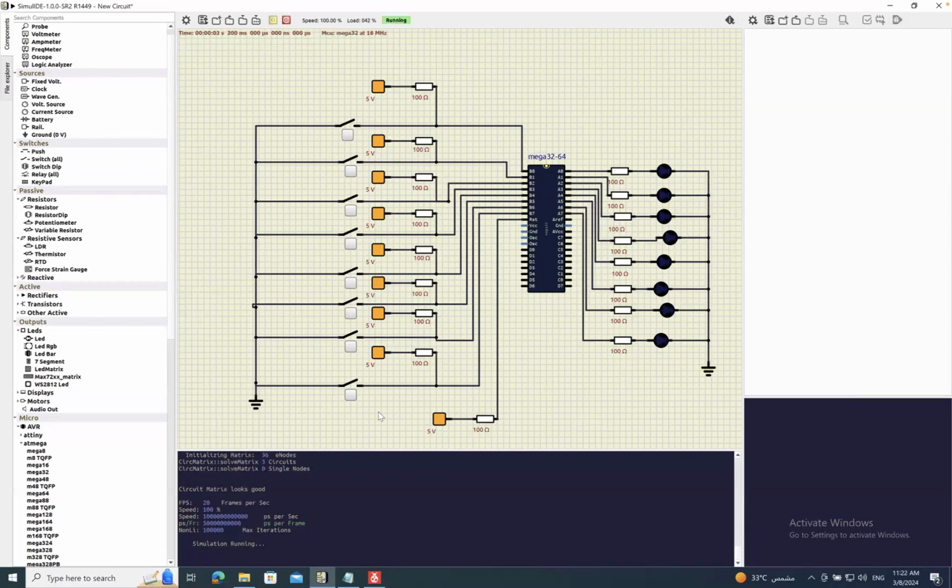Okay. So we want to see what's the value before we press the switch. So we can bring from here a probe and, for example, put it here. Okay, wow. You'll see here before closing the switch, when the switch is unpressed, the value going to the microcontroller is 5 volts.